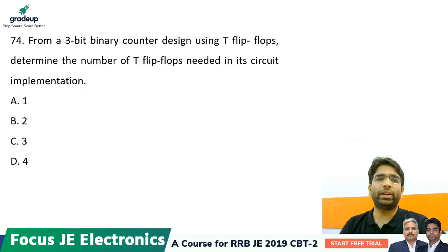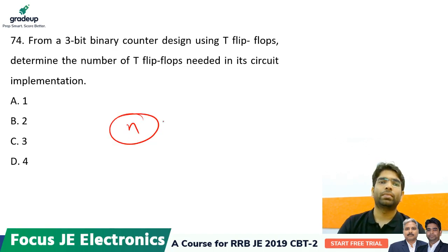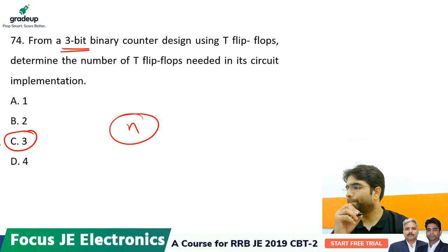From a 3-bit binary counter designed using T flip-flops, the number of T flip-flops. See my dear friends, again a 3-bit binary counter. I already told you that for an n-bit binary counter, the number of flip-flops required will be n. For a 3-bit binary counter, the number of flip-flops required will be 3. Okay.